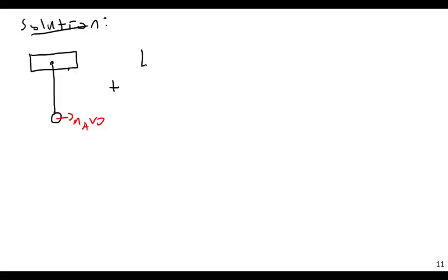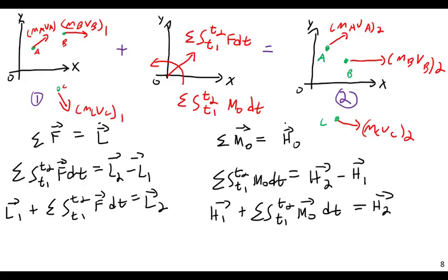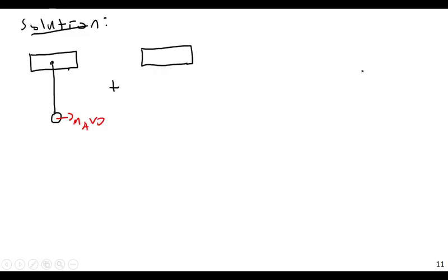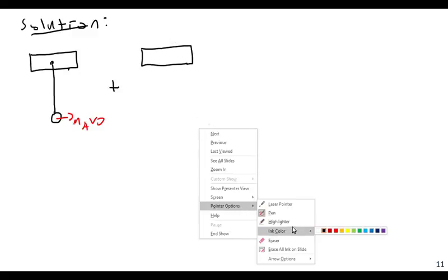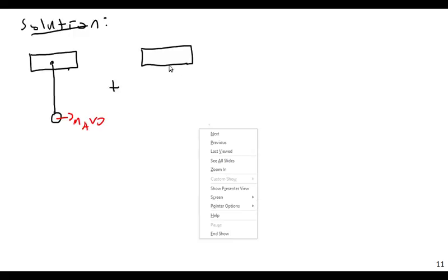What I'm doing here is, look, I'm coming back to this. The initial momentum plus the integration of any forces must equal the final momentum. I'm applying the impulse-momentum theorem. So this is the initial momentum plus any forces, and these forces, let's see, they're all vertical.